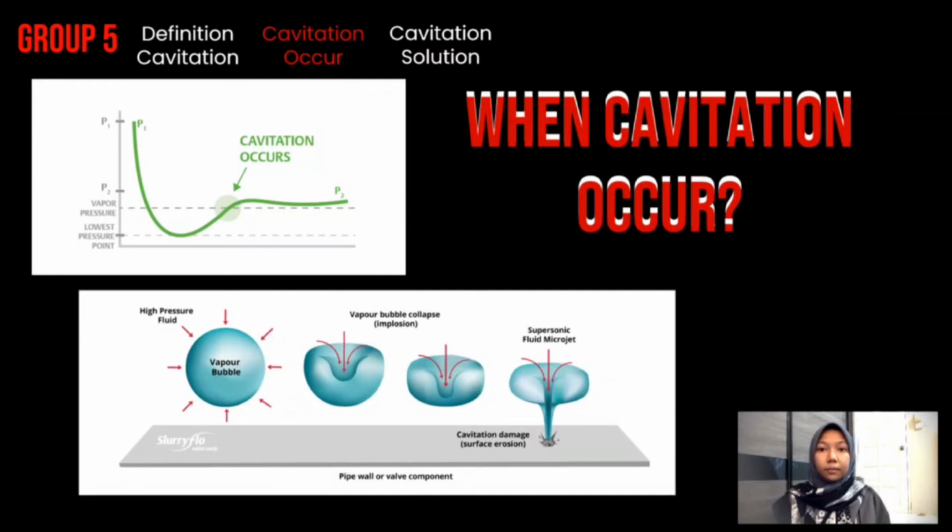The collapse of the bubble causes the gas inside to pressurize and heat up, and a shock wave forms with high pressure and temperature. Noise and light may also form. As mechanical parts may cause cavitation, these shock waves can occur close to the part surface, causing damage and pitting. The pitted surface causes more fluid turbulence and in turn causes more cavitation. Thus, cavitation continuously damages the surfaces and facilitates the corrosion of the metal.